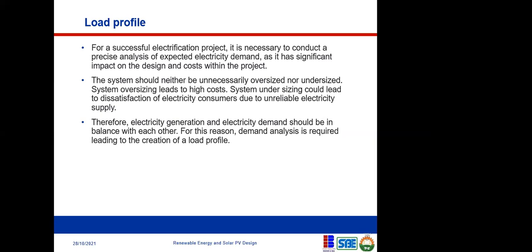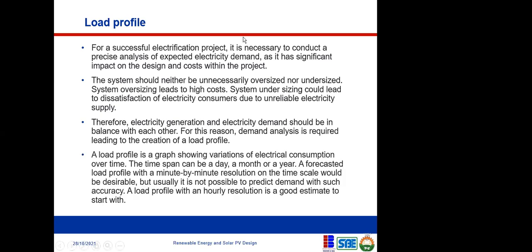For this reason, demand analysis is required, leading to the creation of a load profile. A load profile is a graph showing a variation of electrical consumption over time. The time span can be a day, a month, or a year. A forecasted load profile with a minute-by-minute resolution on the time scale would be desirable, but usually it is not possible to predict demand with such accuracy. A load profile with an hourly resolution is a good estimate to start with.